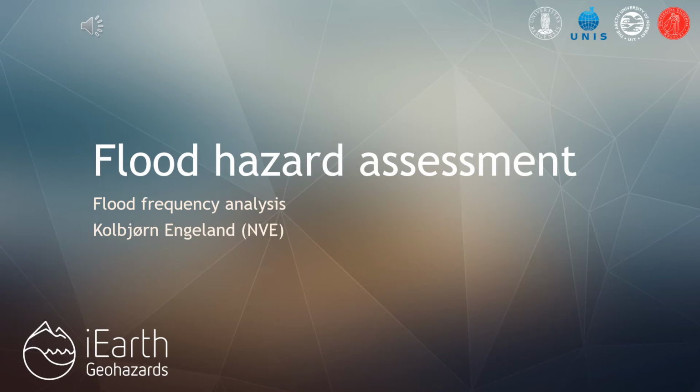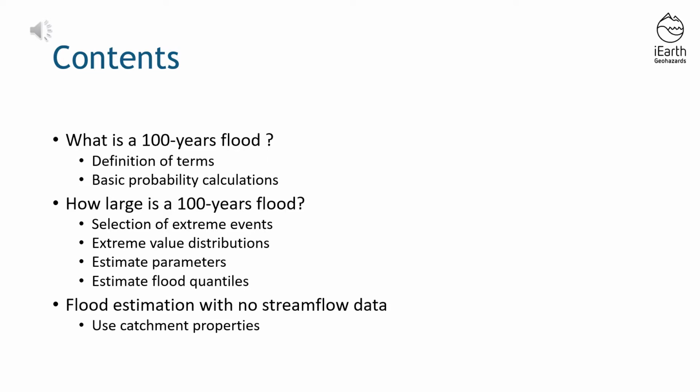Welcome to this brief introduction to flood frequency analysis. First, the contents of this presentation. I will start to define what is a 100-year flood by defining some basic terms and doing some basic probability calculations. I will then show how we can estimate how large is a 100-year flood, how we select the extreme events, which extreme value distributions are used, which approaches we use to estimate the parameters of the extreme value distributions, and finally how we estimate the flood quantiles.